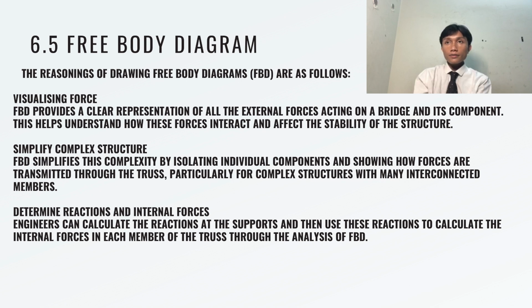Free body diagram. The reasons for drawing a free body diagram, or FBD, include visualizing force. An FBD provides a clear representation of all the external forces acting on a bridge and its components. This helps understand how these forces interact and affect the stability of the structure. Other than that, it simplifies complex structures. FBD simplifies this complexity by isolating individual components and showing how forces are transmitted through the truss, particularly for complex structures with many interconnected members.